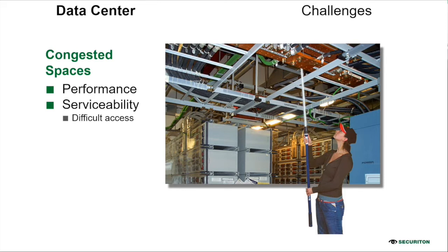Second, you can reduce the area covered by one detector or sampling point significantly if you use a proper system. Before doing everything, you have to refer to the code relevant in your country. For details, you can take a look at NFPA, FM or VDS guidelines.